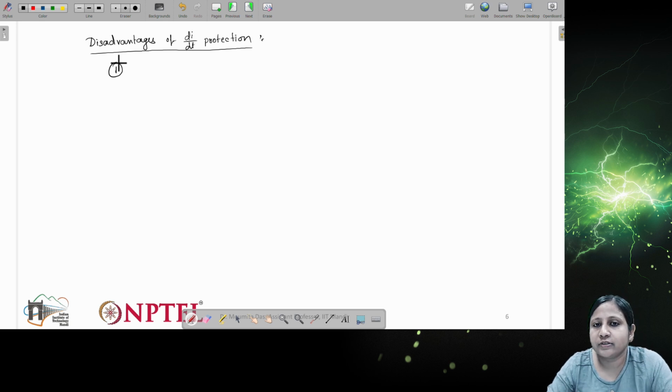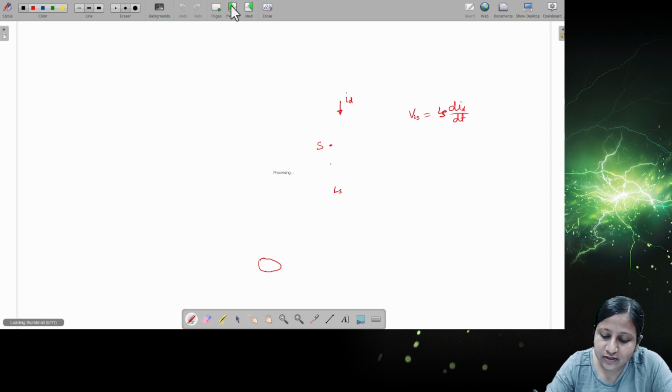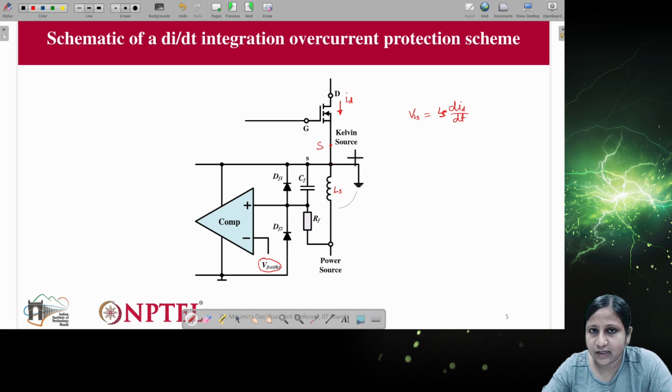It is very small. At the chip scale level, where all the different points are connected, drain, source, gate, the chip size is very small with respect to silicon. Then the LS that I have represented here is generally much higher in the case of silicon devices, and also in the layout which we generally consider for silicon-based converters. So from the layout also comes this parasitic inductance.